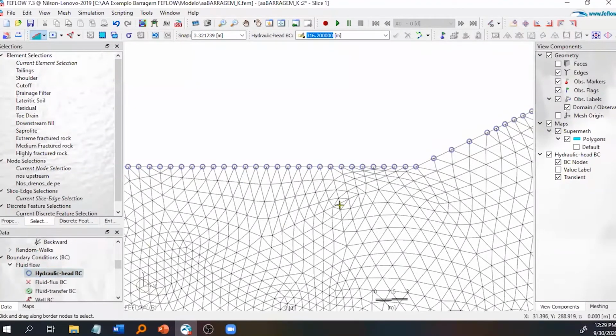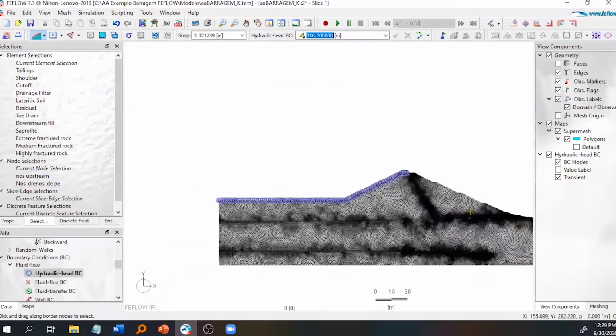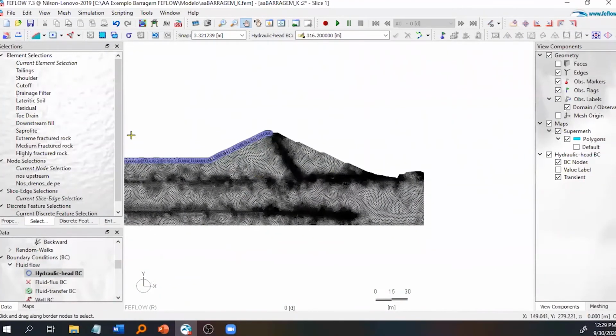to non-hydraulic heads. On this side of the model, we are going to assign that this is open, everything here is open to atmosphere. And open to atmosphere means that as long as the flux is leaving the system, the head becomes constant to that elevation.